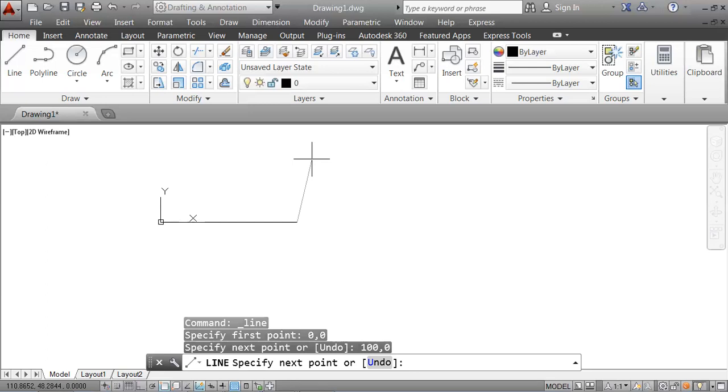Here is the problem of this absolute method. Now, if you want a line to go 50 millimeter up, right? You have to keep in mind what was the value of the last information you typed. You have to remain at the last x value for the next point.